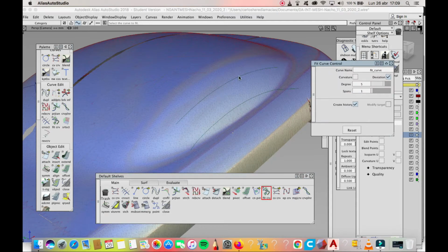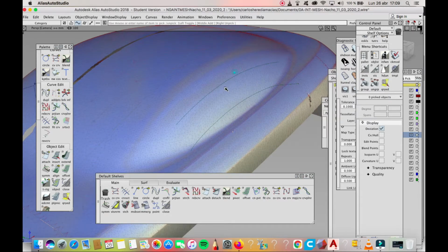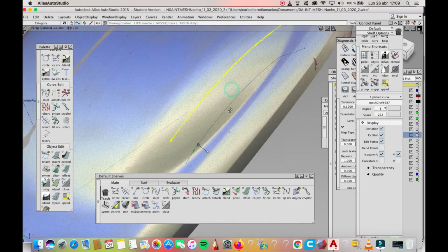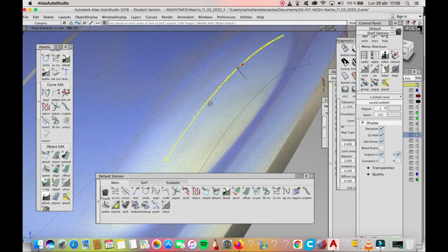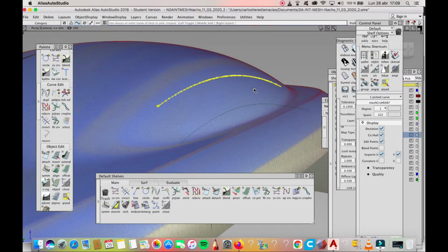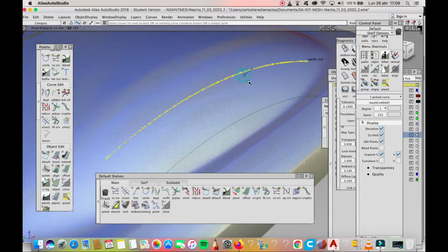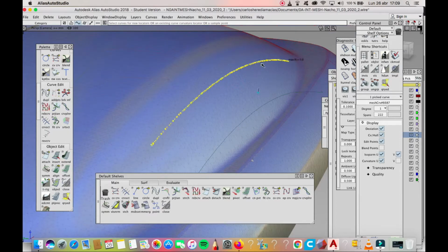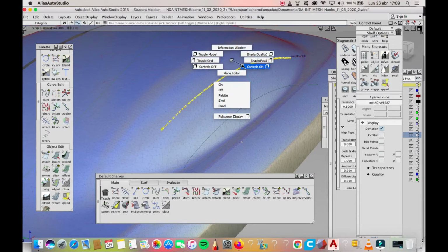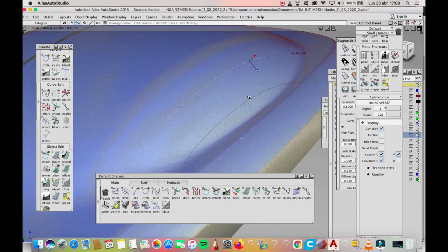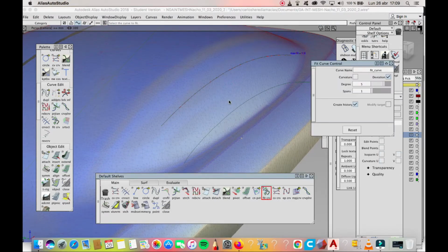Okay, so right now these are curves that have a lot of CVs. If we try to get the control polygon, you will see that we have a lot of CVs, and if we put a curvature plot, it's going to be a mess, and this is not usable. But we can create a curve from this one that's going to be shaped in a better way.